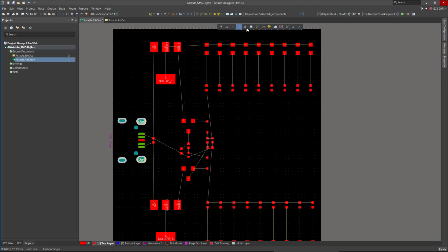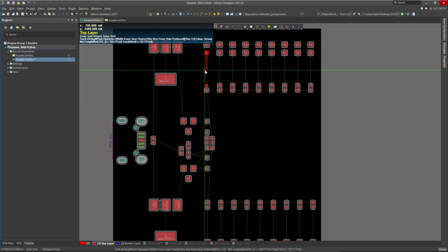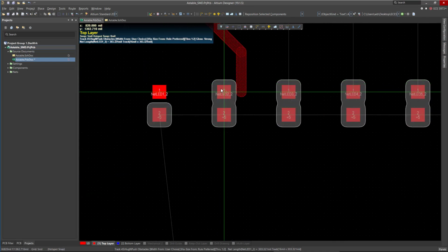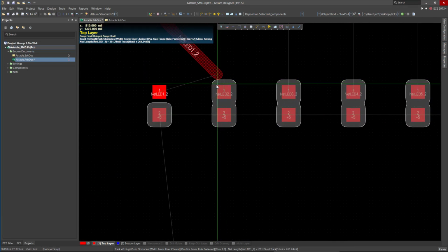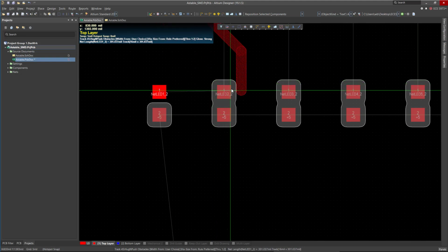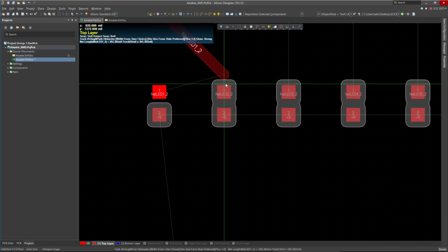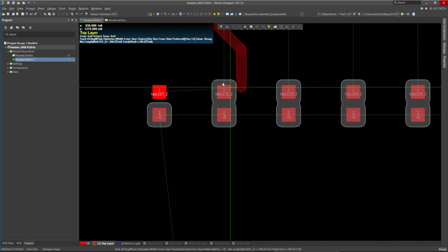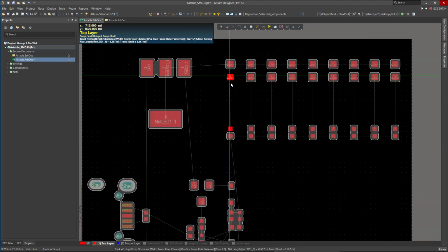So now you can select the route from here, or you can select Ctrl W. Now when you click on this, you can see how the other pads are isolated. If you try to come closer to this pad, you won't. Basically the trace is pushing the obstacles and hugging the obstacles. This is the routing mode now, and we will talk about these modes later, but now you cannot get closer to any trace or pad that doesn't belong to the same net.